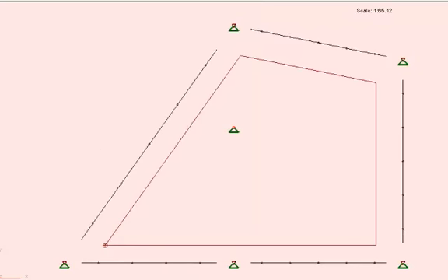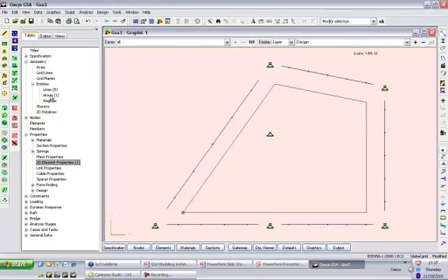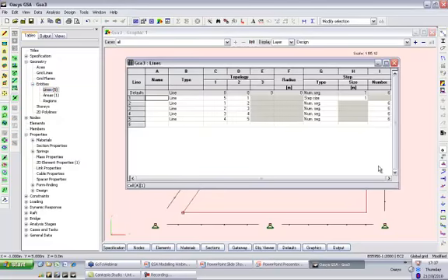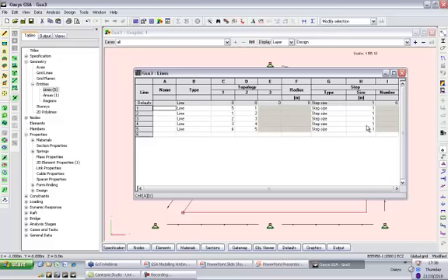I often find the step size gives a slightly better mesh, and you now have a table view to actually set these up. So if I just set my defaults and just correct those, this is coming in blank at the moment. It's not really blank, it's just the graphics that haven't updated, so there's nothing to worry about there.